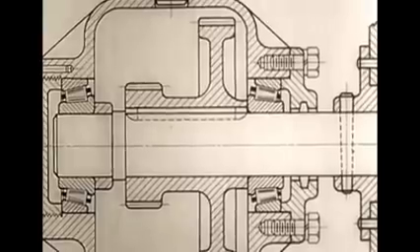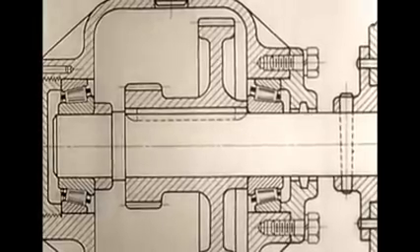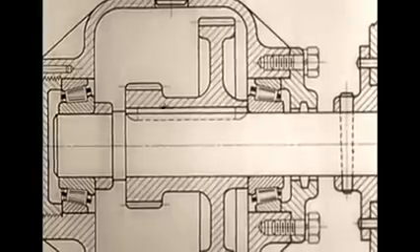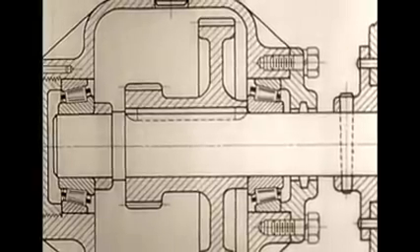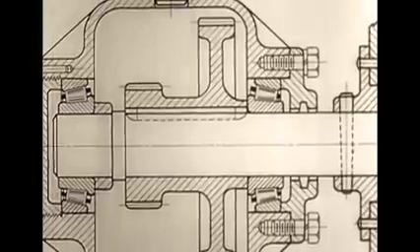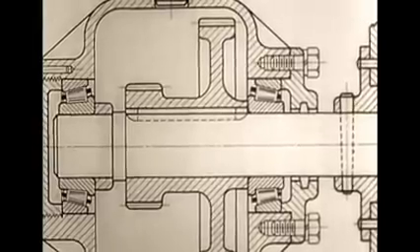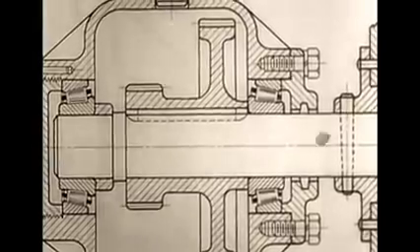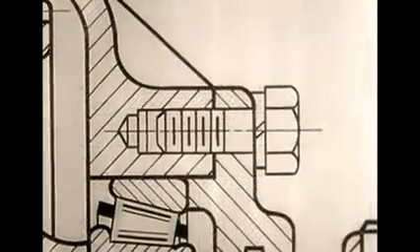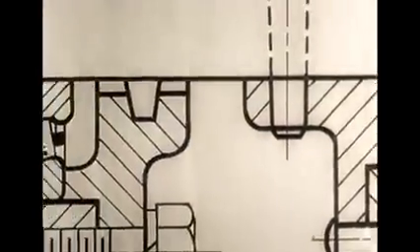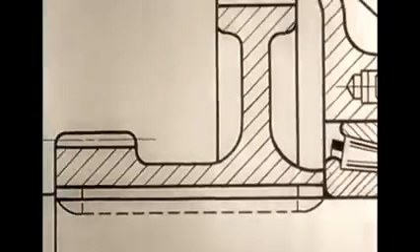You can make your drawings clear and easy to read by following certain rules in section lining them. Do not section line small parts which have no inside details, but show them full as if the cutting plane did not pass through them. Apply this rule to shafts, to bolts and nuts, to rods and rivets, to keys, and so forth.